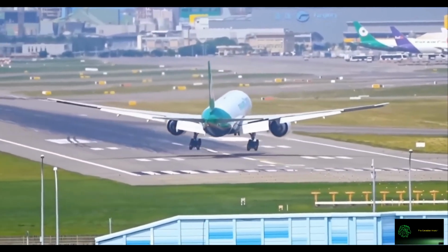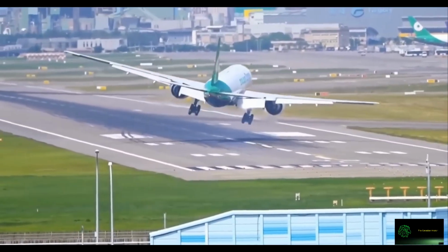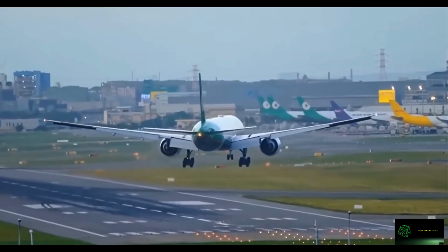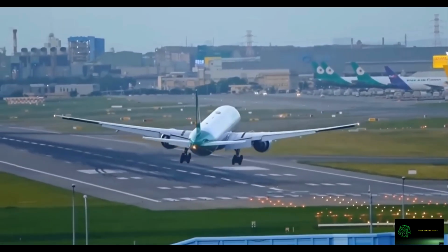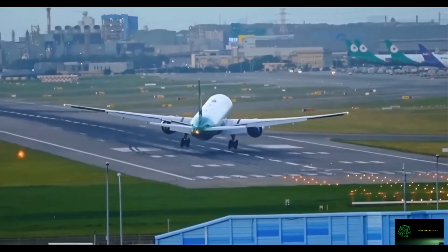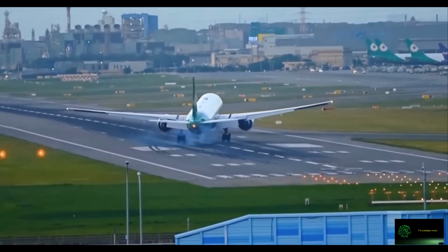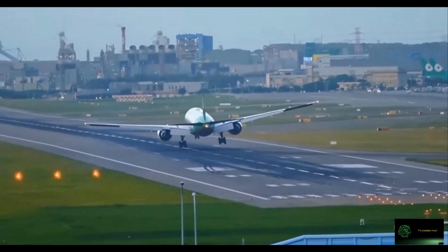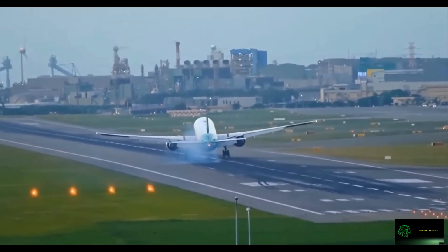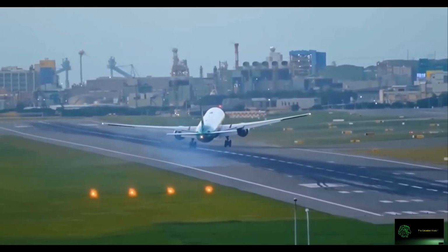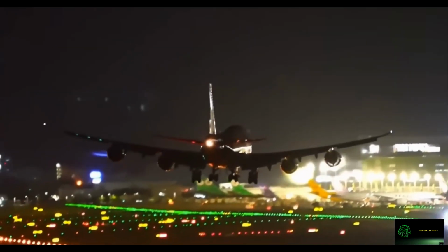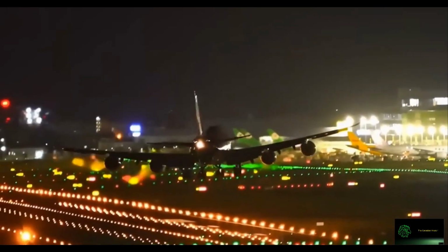At or below VB, the aircraft can better absorb sudden gust loads because the wing will tend to stall before structural damage occurs. Flying above VB in turbulent conditions increases the risk of overstressing the aircraft. VB is not normally marked on the airspeed indicator and is found in the aircraft performance or operating handbook.